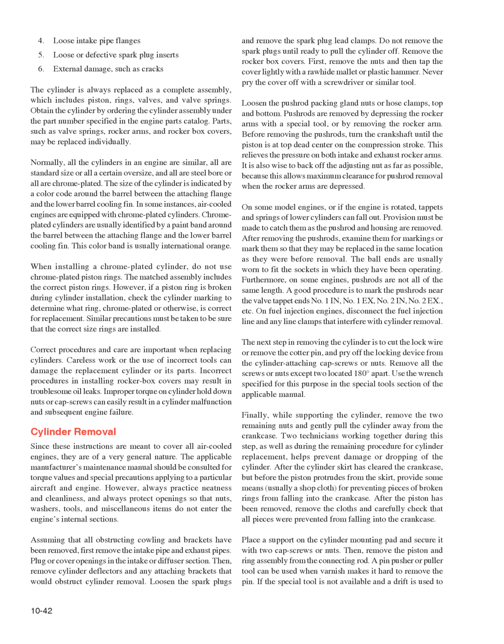When installing a chrome-plated cylinder, do not use chrome-plated piston rings. The matched assembly includes the correct piston rings. However, if a piston ring is broken during cylinder installation, check the cylinder marking to determine what ring, chrome-plated or otherwise, is correct for replacement. Similar precautions must be taken to be sure that the correct size rings are installed.